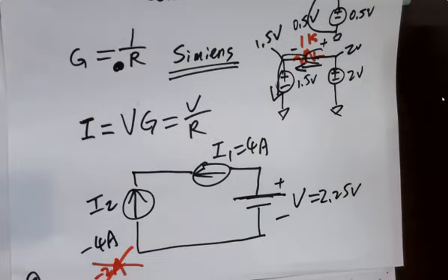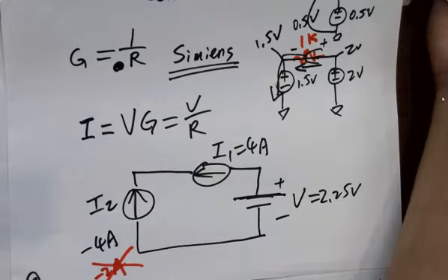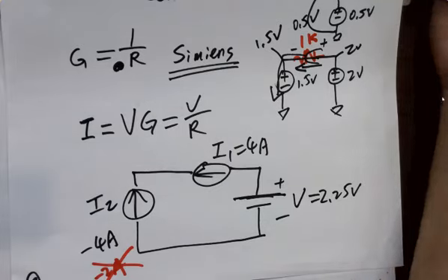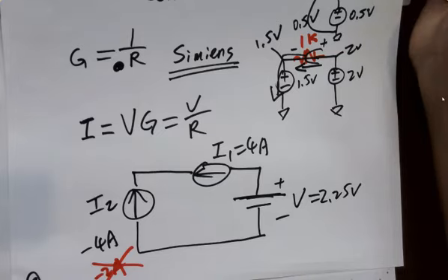In practice, is the internal resistance going to come out to be pretty close to 0? Yes. So voltage sources have an internal resistance very close to 0, always. That's how they are designed. You know why? Because they want to deliver the voltage to the outside world instead of dropping it internally.